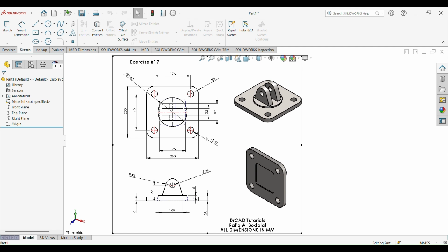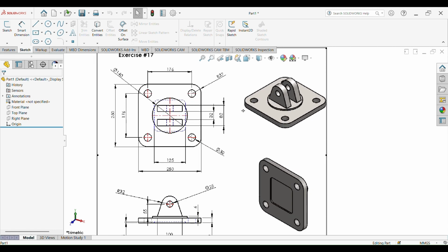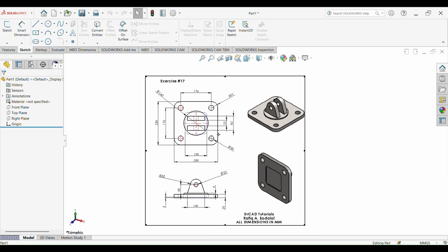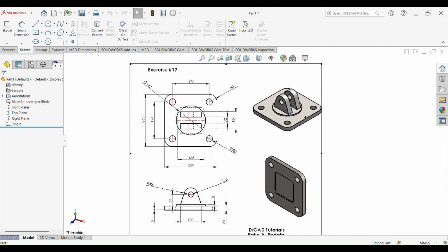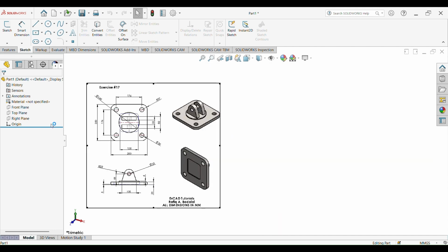Now, if we look at the schematic diagram here, the detailed drawing, I think the easiest step to begin modeling this in SolidWorks is to work on the base here, right? So the base is a square with a fillet radius to the edges here, and there are 4 holes at each corner. Of course, we're going to be implementing the extrude boss base feature to create the thickness of the base. So let's get started.